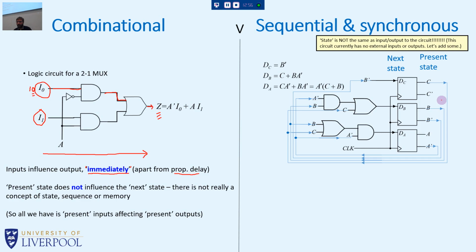So what would be logical here would be, if you remember the 7-segment decoder circuit, where we could hook something up so that we get a binary input and we'd output a 7-segment display. Well, if this is a counter, I can't remember which counter this is, but let's say it's cycling through from 0, 0, 0 to 0, 0, 1 to 0, 1, 0, 0, 1, 1, and so on, then what would be nice is to connect up some 7-segment decoder circuitry so we could display what's happening here on a screen in decimal. So that it would cycle through 0, 1, 2, 3, 4, 5, and so on.